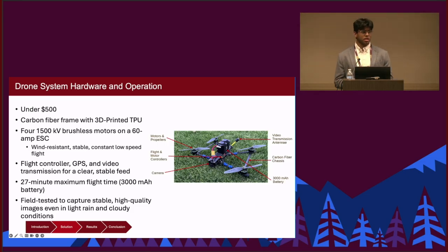And an unintended advantage of using drones in this use case was that the prop wash, or the thrust wake of the propeller, actually blew onto the leaf and helped disperse the leaves of the plant, helping create a more clear image of each individual leaf. And in this use case, we used 5-inch propellers with a very minimal pitch, again to help reduce the effects of wind and create a more stable image, at the expense of having a slower moving drone, but we realized that was not a need for this use case.